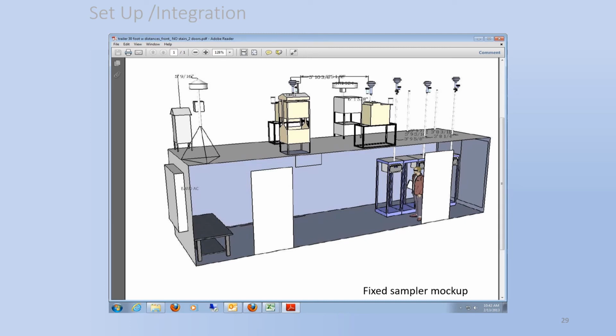Again, it's best to consider BAM penetrations as a fixed point that will typically have to be worked around when determining if there is adequate space for the rooftop samplers to maintain the 1 and 2 meter distances between sampler inlets. If we could add individual circuit locations into this, we'd really have something. Also, one trick we borrowed from Ventura County was to turn our racks at an angle so that they're easily accessible from the front and back, and the interior space is optimized.